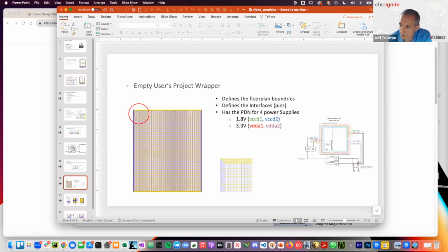Yeah, so if you're implementing an accelerator, one model is to implement that accelerator and connect it onto the wishbone bus, and then run traffic to it from the management area. So that's one model: you could implement an accelerator and integrate it into the Caravel design. I hope that covers that one. Please post again if we missed something or you need further clarification on any of these.